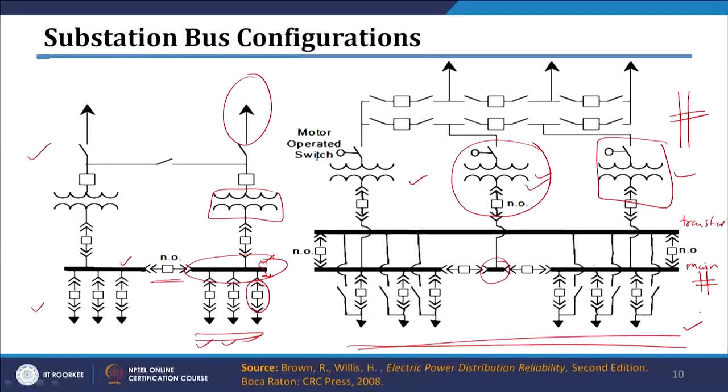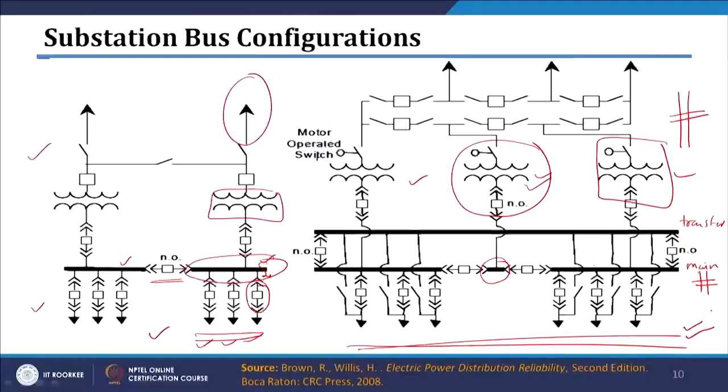However, the cost involved will be much higher than your simple substation, which is shown on the left hand side. Also, the relaying scheme or protection scheme for this bus configuration, which is shown in the right hand side figure, will be more complex.